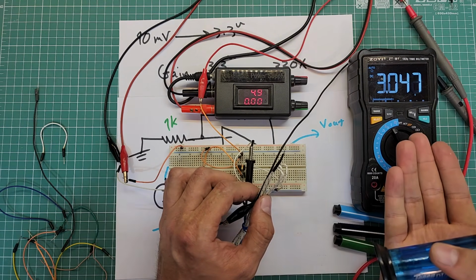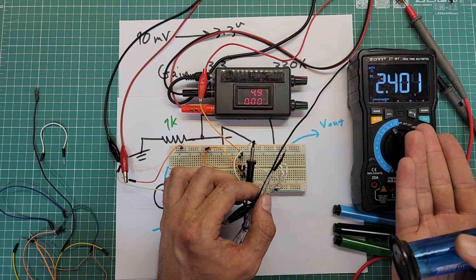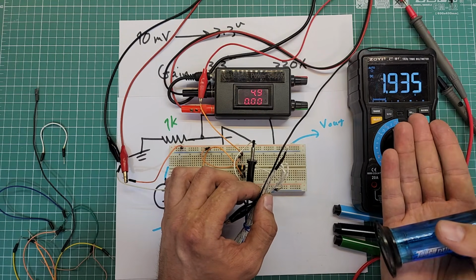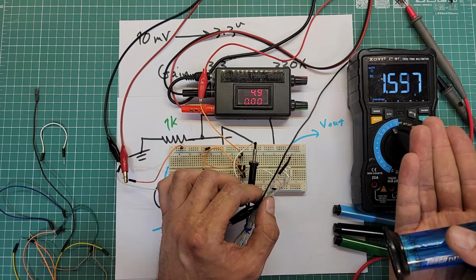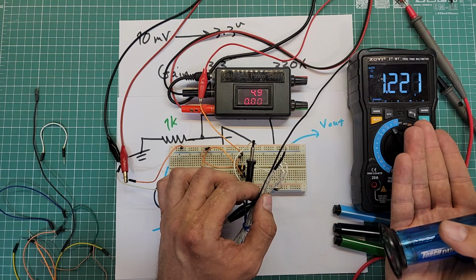Now that the voltage is amplified, we have a variable voltage from 0 volt to 3.3 volt, which can be easily read by any ADC unit. Thermocouples are widely used in industrial equipment and their usage will be restricted without an amplifier. Anyway, we are moving on to the next application.